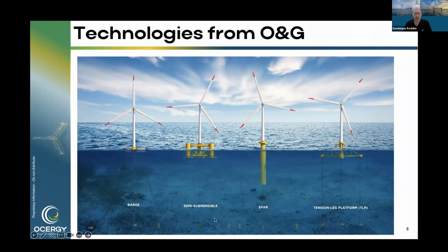Why the spars? Because the wave exciting force is what happens on the bottom of the spar. In this case, it's very deep and it's very small. On the TLP, you have very little motion because your stability comes from the fact that your tendons are under tension, so they compensate the first order loads, what's coming directly from the wave. So those are excellent platforms for dry trees. The semi-sub is a wet tree platform, meaning you have a flexible riser that goes to the seabed, and the control of the well is on the seabed. Cheaper, but some restrictions on vertical motion.